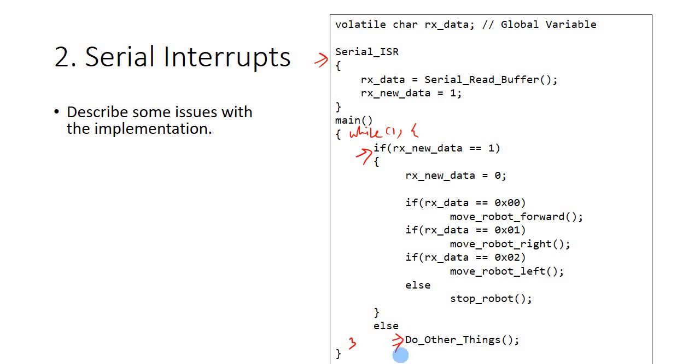One of the things you can see quite clearly is that if I miss this check, and after I complete this check the ISR is triggered, then I would have already been busy doing other things. And these other things could take very long. Because of that, it will not be an immediate response to the data that has just been received by the controller.